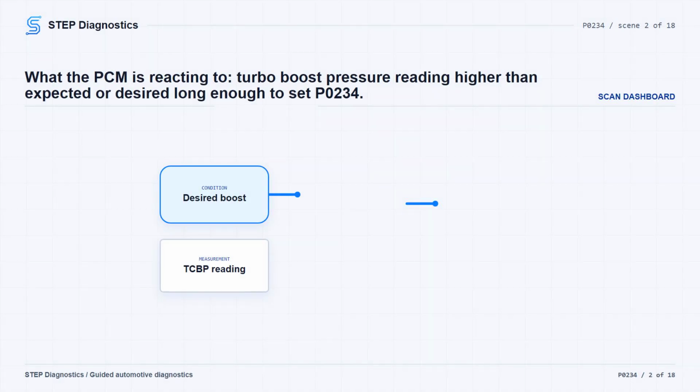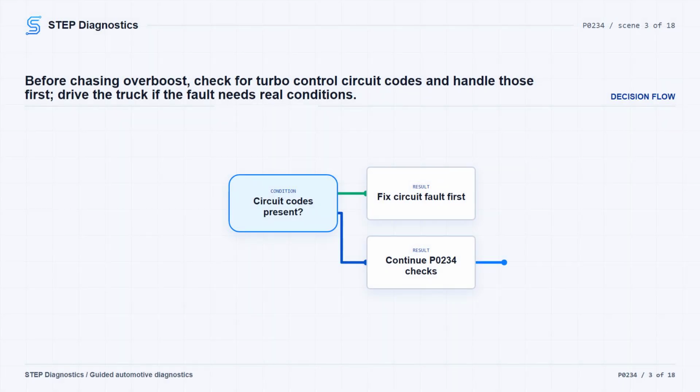Broadly, this can involve an intake air or charge air concern, a turbocharger bypass valve or bypass circuit concern, a turbocharger wastegate motor concern, or a possible PCM concern. Treat this as a controlled diagnosis, not a parts call. This level of testing assumes you're comfortable with Ford-style scan tool PIDs, circuit checks, and boost control operation. Start with the basic system checks.